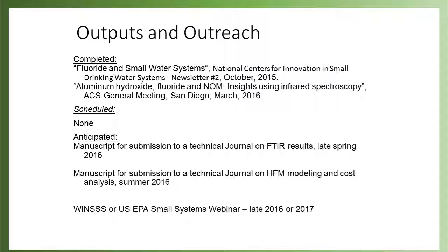In terms of NOM, again. In terms of NOM. It's similar at higher pH, like 6 and 6.5. It's a pretty similar remover for both ferric chloride and alum. But as you moved up a little bit, it was less for the iron. Yes. So 6.5 is still pretty low for a system. For our system, yeah. But where we have in the past changed from alum to ferric at around the same pH, we typically did better. Okay, it's good to know.